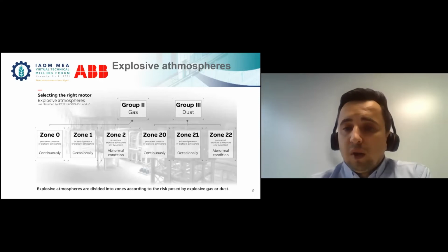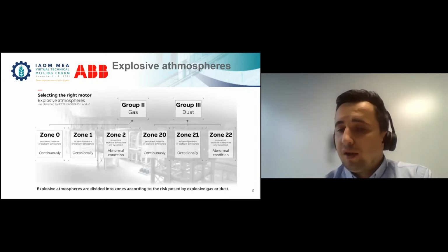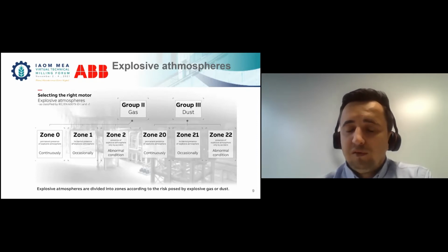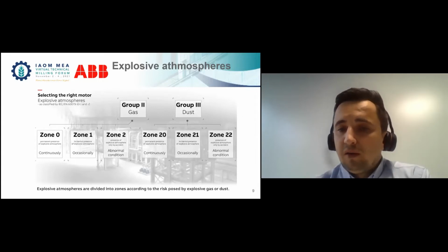Then there are also grain milling industries, which are often in a hazardous area because of dust. So then you have to select the proper motor for this specific installation place according to your requirements.